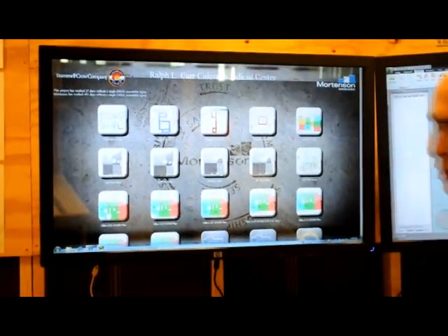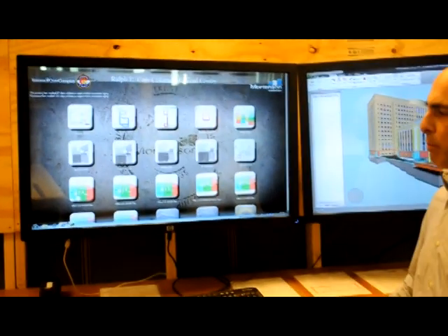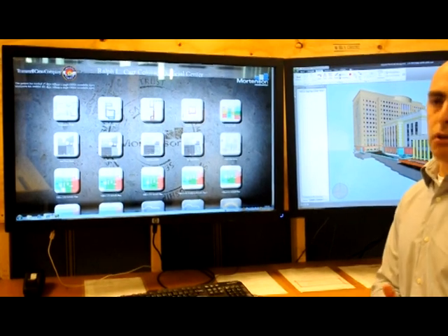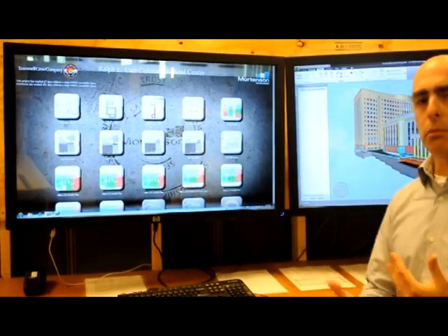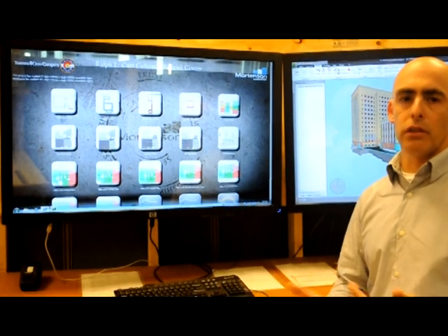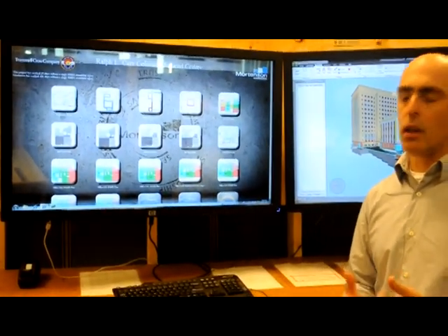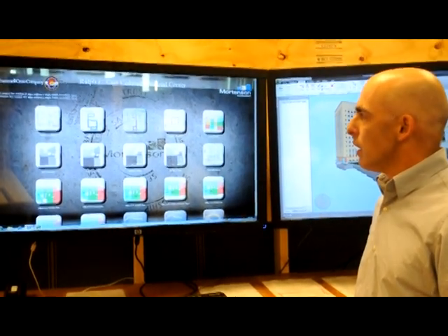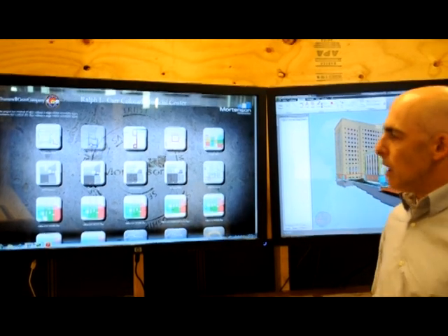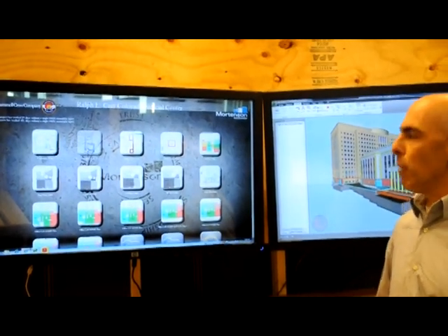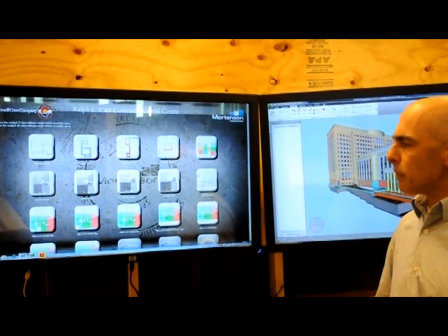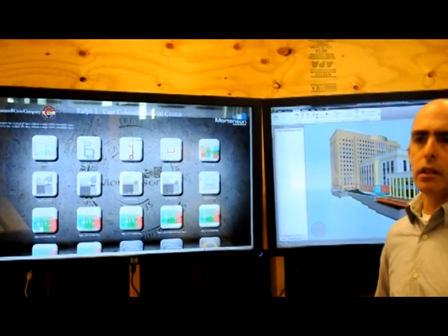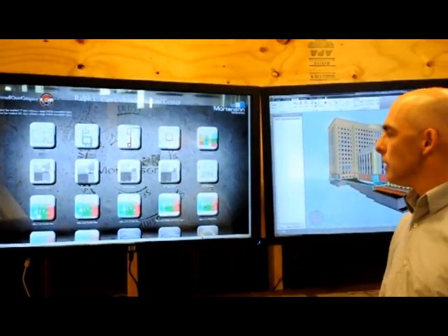So just going back to our lift drawing process, lift drawings are basically generated from a model. We take the model that we get from the design team, and then we insert all the knowledge from our superintendent and our field team, as well as any shop drawings that we need to create. And we basically create a model that we can use for that purpose. And from that we create the 2D representation that our guys take in the field to actually build the project.